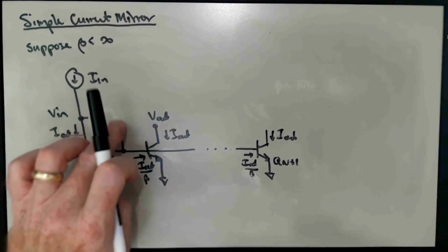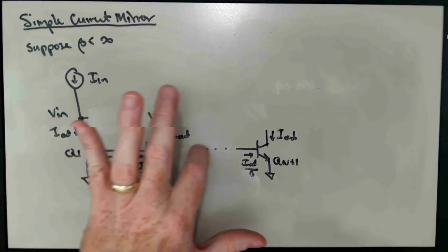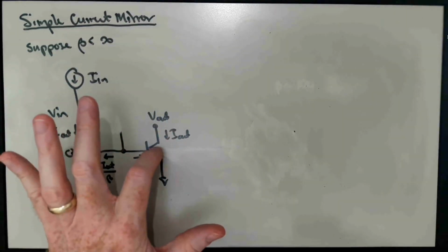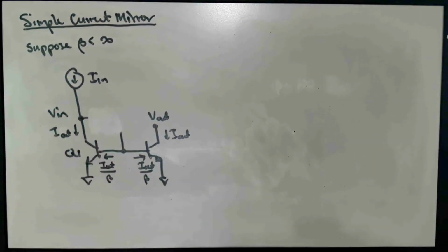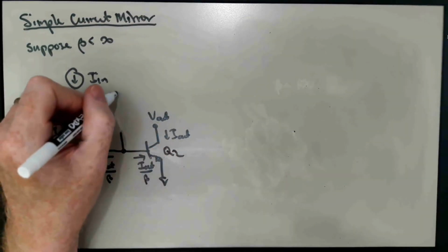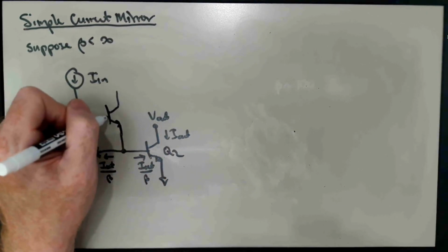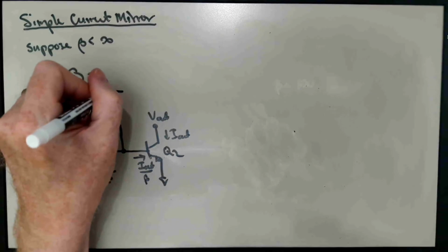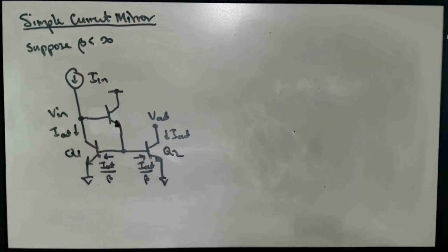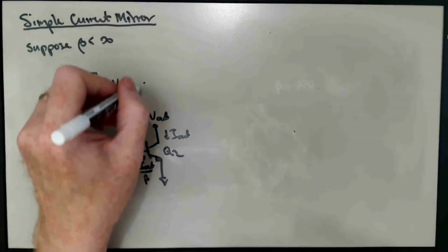But another thing we can do, which is fairly effective, if I go back to our two transistor case, Q1 and Q2, I can just use a single NPN transistor, which is basically like an emitter follower. And we'll tie this up to VCC.